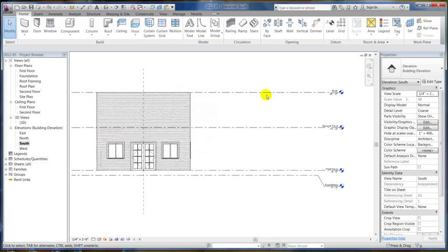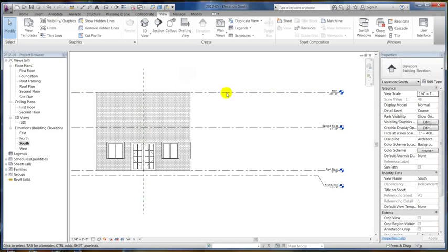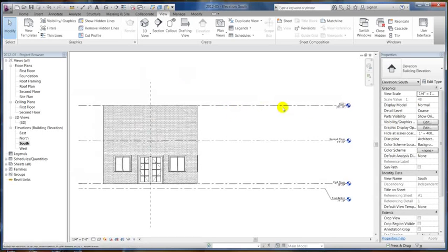So what if my roof was at 20 feet and let's say I had another level? I can have a parapet level, so I could have my roof actually down here. Let's go ahead and do that. We can go to view and we'll create a level. I'll put a couple levels in here. We'll take them out because I'm not going to use them, but I just wanted to show you how to do it.